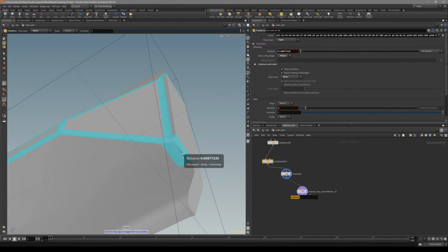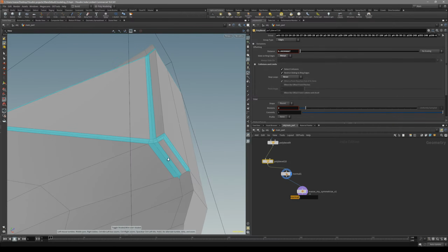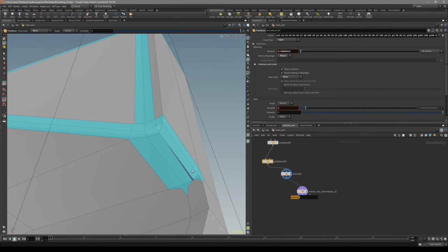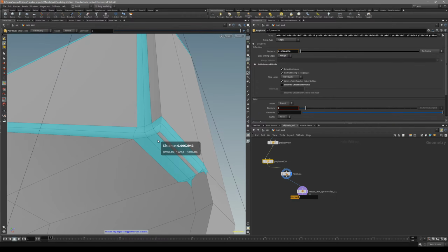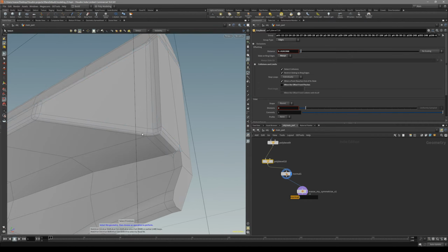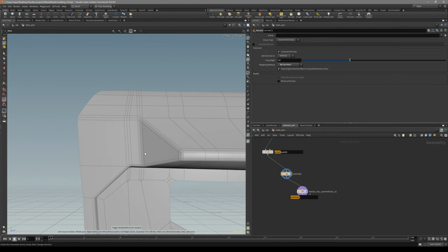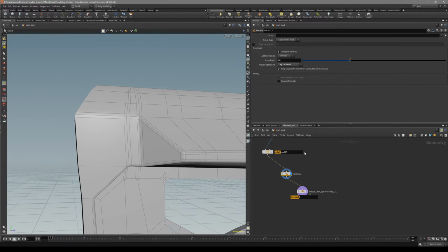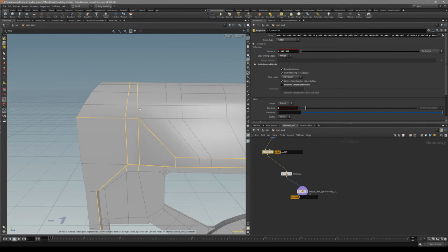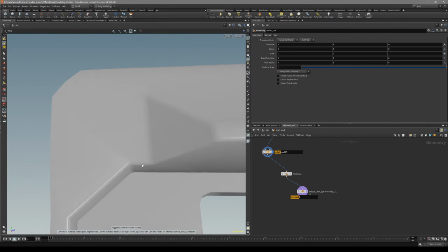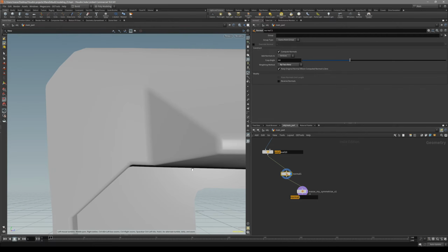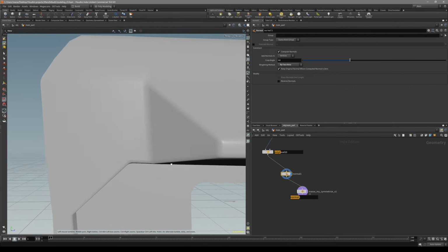See, there's a problem in here, so you have kind of over beveled it in here. Let's put it to individually, so we do not over bevel it in here, like that. One more thing, maybe let's not bevel this edge, so let's go back to our bevel and let's reselect it. So let's not bevel this, let's just bevel until here, like that. And with the face area normal, let's get that nice result.